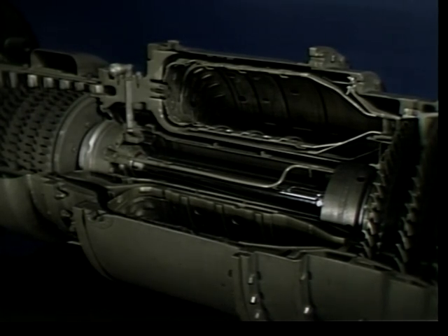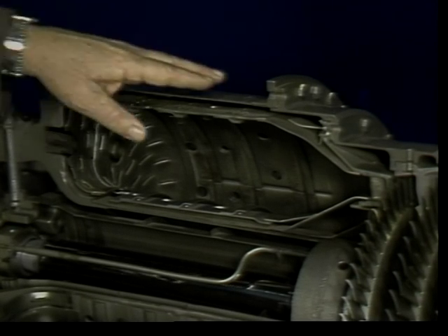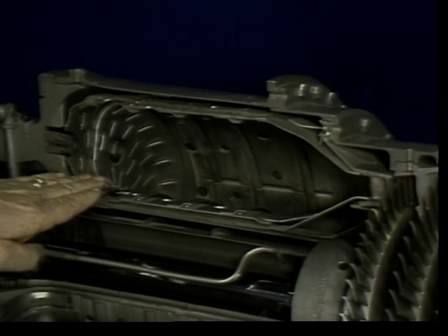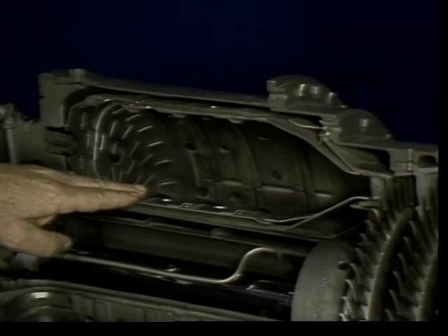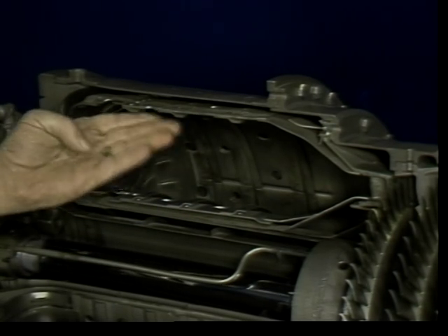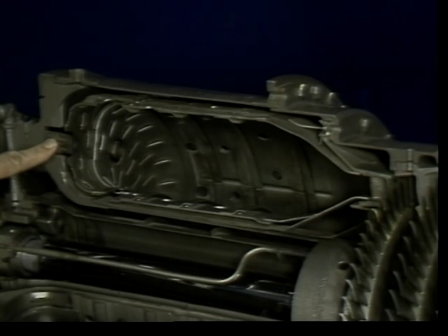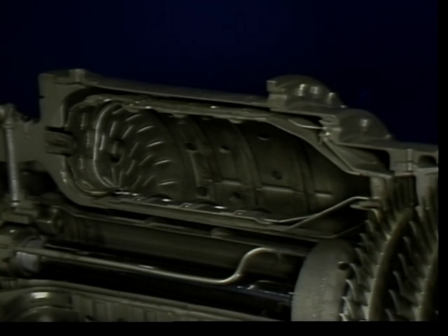place. The combustor assembly consists of a case, combustor dome, combustor inner and outer liners, shrouds, and the fuel manifold and nozzle assembly. An igniter plug, compressor discharge pressure air lines, fuel air lines, and fuel drain fittings are installed in the case.